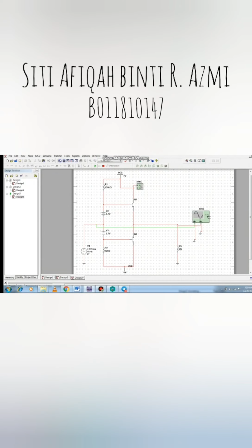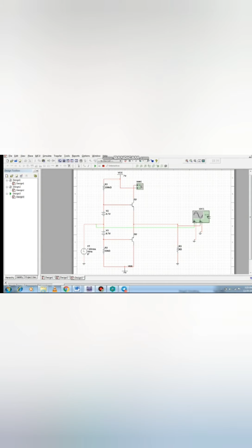The crossover distortion is the problem that occurs when both the transistors are off at the same instant during the transition period. In order to eliminate this, the condition has to be chosen for more than one half cycle. Hence, the other transistor gets into conduction before the operating transistor switches to cut-off state. This is achieved only by using class AB configuration as shown in the circuit diagram we draw.